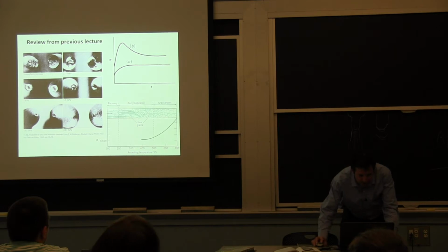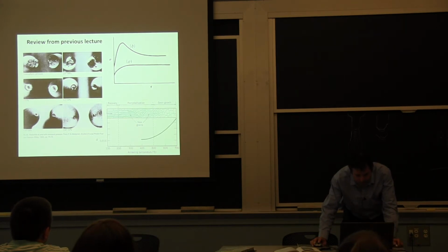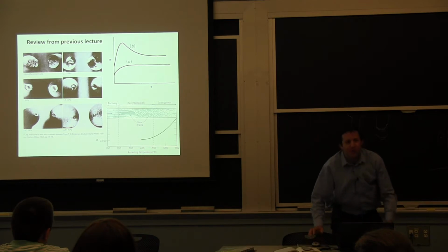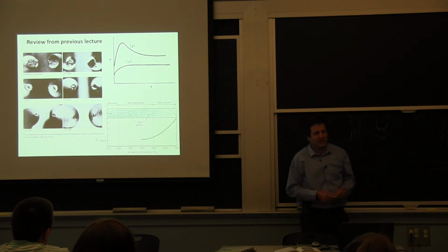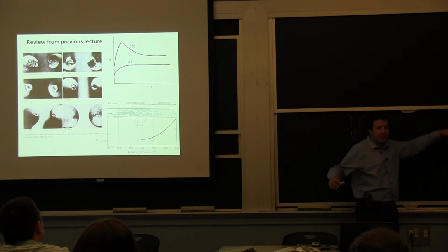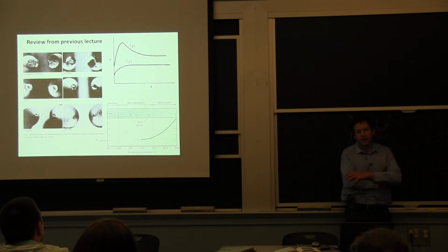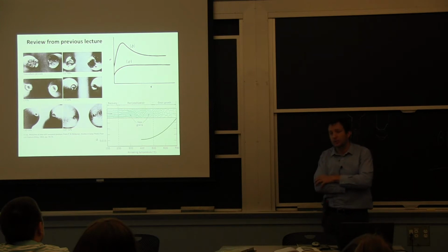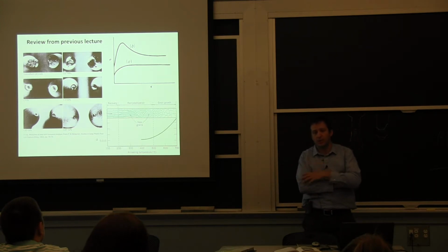So if we start from here to here as the diameter of the central portion, it's going down here, maybe by half. Here it's about half of what it was over here. Keeps going down. Here you have a little bit, and here it's almost going to a single point. That's because you are preventing the formation of the voids by superimposing compression in the whole volume of the specimen. So you get more deformation.